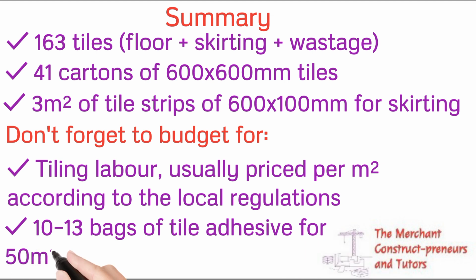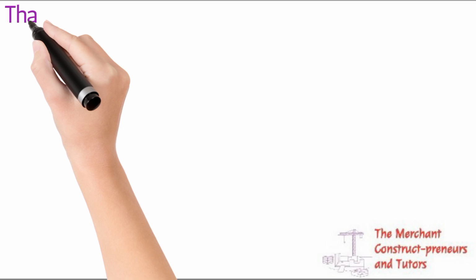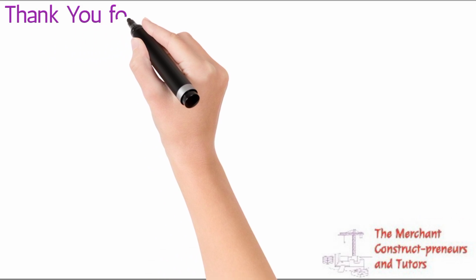Then for the tile adhesive, we said 10 to 13 bags of tile adhesive. With one bag, we make 4 square meter, right? So with this information, I believe we'll be able to estimate the tiles needed for any type of job in a building, from the small scale to a larger scale. Just watch the video again to check if you are confused about any point.